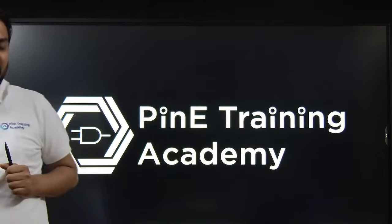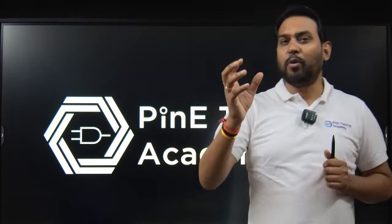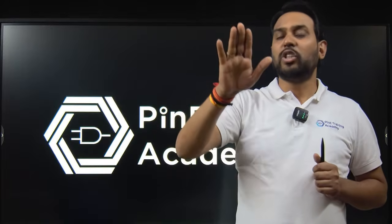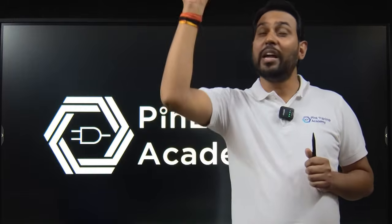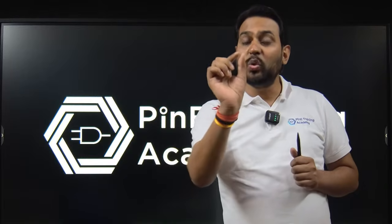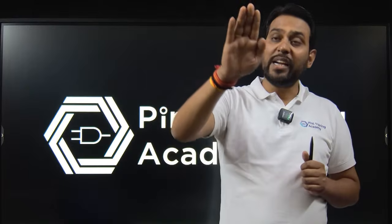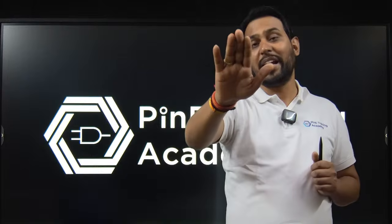Similarly, I will give one example. In my BTech time we used an LDR, a light dependent resistor, and we made a project with sunlight and a solar panel. The solar panel is fixed, but we can move it according to the intensity of the sunlight. So I use the LDR to find the intensity, and by this intensity it can control, okay, this intensity is good, so it is maintained like this.